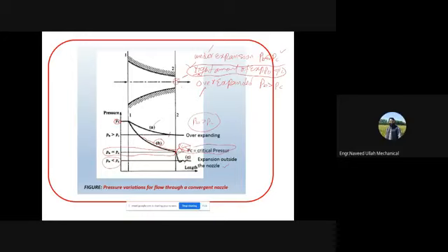The jet is coming out of this section, and since in the over expanded case the back pressure is greater than the critical pressure, it tries to compress it. You see that the expansion completes its decrease before the section. So this is your over expanded nozzle.